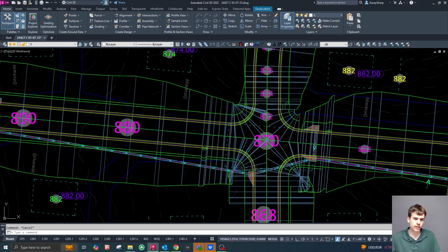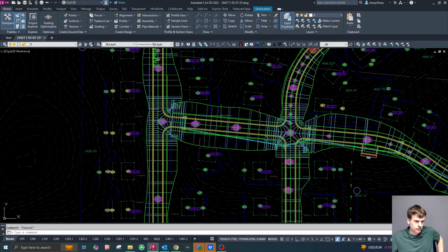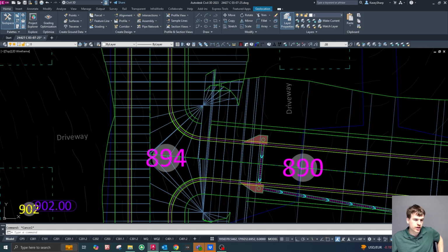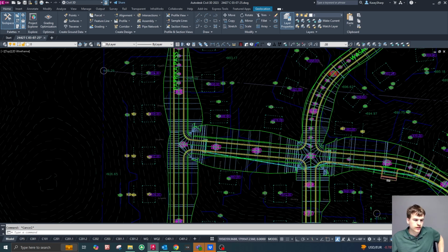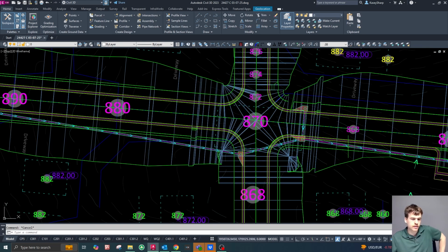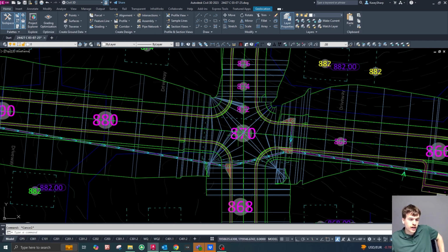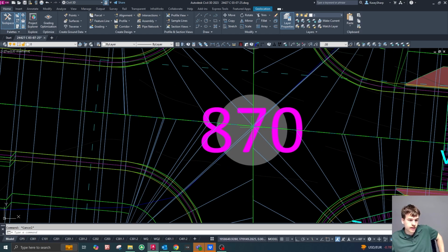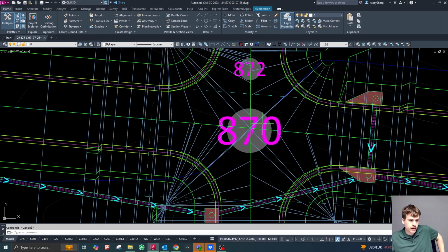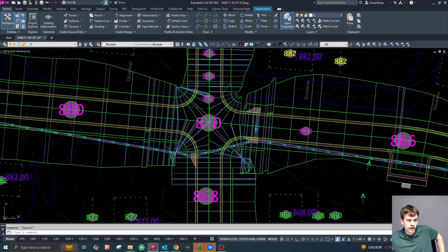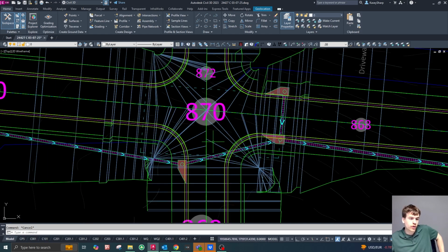I'm going to go ahead and freeze those alignments again. As you can see up here on this intersection, there's a bow tie on each one of these corners. Sometimes that clear bow ties works, sometimes it doesn't. I usually don't spend the time doing that. Okay, but once you've changed the targets and edited the target mapping for each one of your regions, your intersection is pretty much done. As you can see here from these blue lines, it's going to maintain this crown here in the middle and then taper off and include the crown for the rest of the corridor on both roads.